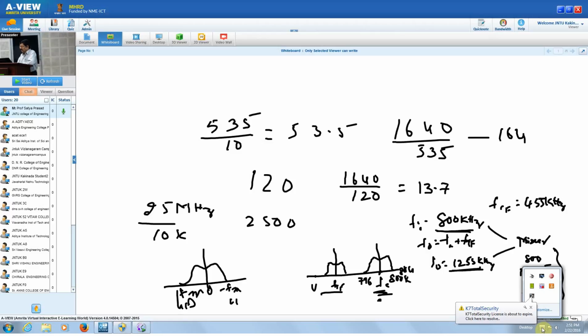The difference is the frequency, and we are tuning or having a circuit at the mixer output. The output has the difference frequency, 450 kilohertz, plus or minus 5 kilohertz that we have around that 450 kilohertz.